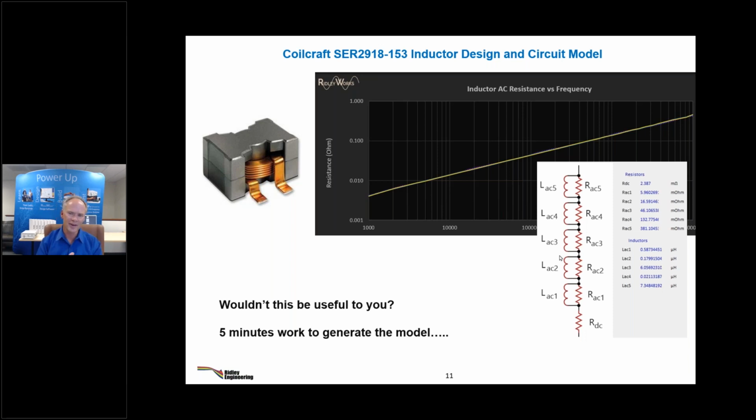The currents will actually move to minimize leakage inductance on a transformer, for example, and they won't use the outer layer of winding. So when you're winding transformers, instead of doing two in parallel, you do the two wires in parallel, and then you do the second winding in series with that. So you're forcing conduction through both layers. That's what you're trying to do. So parallel windings, you have to be careful with that.